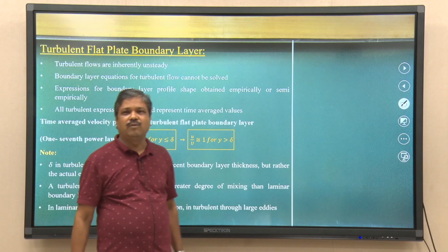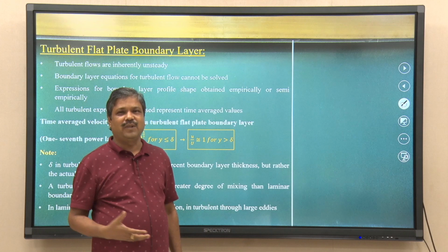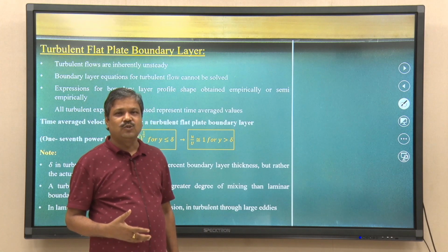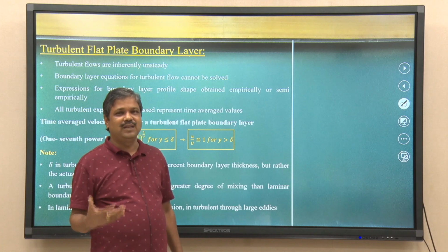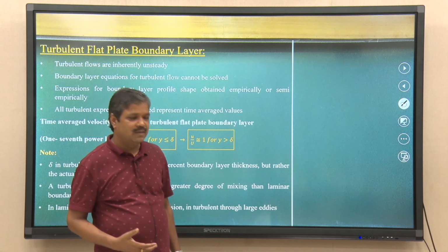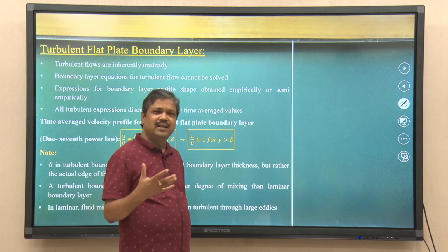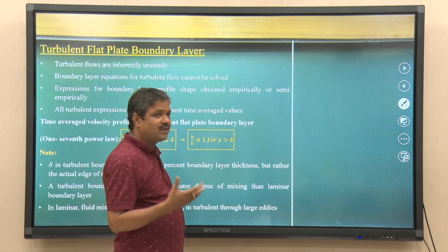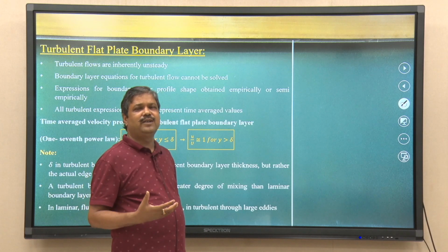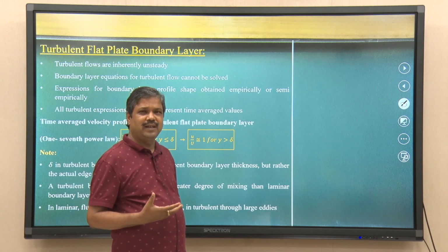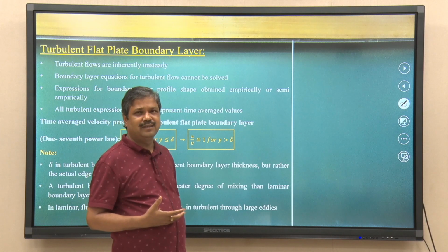When you go to turbulent boundary layers, I will just discuss conceptually with you. The equations come out very complex. So, for turbulent boundary layers, we basically do not get hand calculations, even numerical techniques are needed to solve these problems, because, as I introduced in a very simple way, turbulent flow is chaotic with a fluctuating part, and the time average components are there. So, instead, people just look at standard formulas that are enough to give the velocity distributions in the turbulent boundary layer regions.